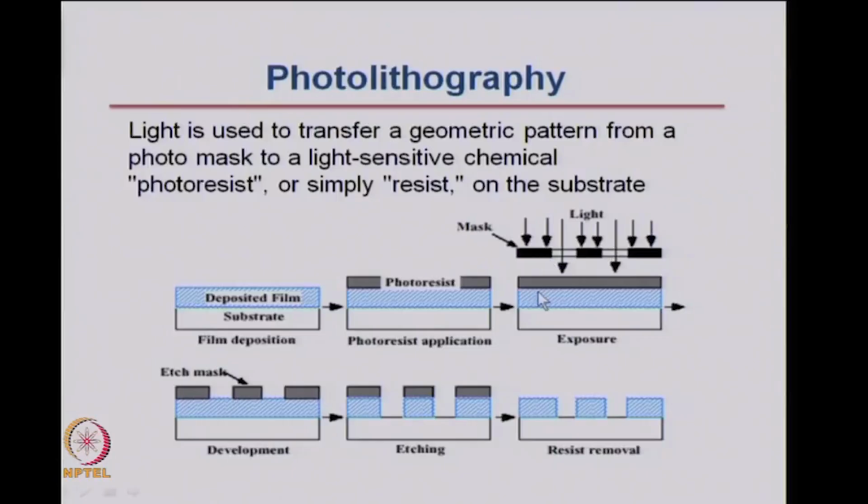So, the mask was on top of this, light was passed and it creates this kind of holes. On top of this film, the mask has been removed and so we etch the mask off and then you can see only the film on top of the substrate and the photoresist is removed at certain parts.